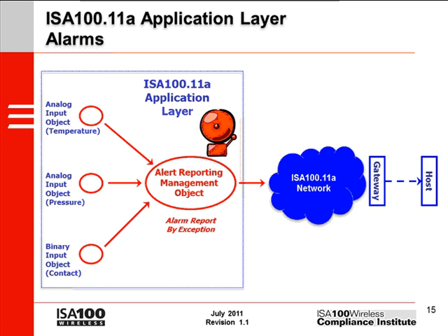Instead, the user might configure devices to report once per minute or something like that. But at the same time, the user can also configure the device to report alarms immediately, as quickly as the network can transmit them. If the network is correctly designed, alarm reporting can be surprisingly quick. Anyway, when you put these two approaches together, periodic publication and exception-based alarming, the result is an optimal balance between energy, data freshness, and fast alarms. The combination is much more efficient and scalable than using either approach alone. Publications and alarms are fully specified by the ISA100 standard as part of the generic application layer.